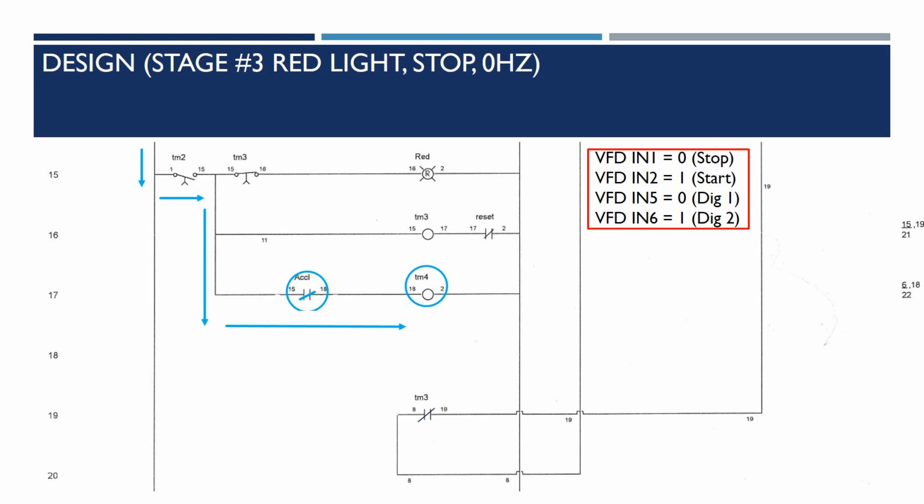That coil has been programmed with a 10-second time delay, which is the penalty that is applied to the boost button. So your 10-second penalty either starts in one of two conditions. When you let go of the accelerator button, that will open that contact back up and shut power off to TM4, which would start the timer, or when we have our normal reset signal and the light transitions back from red to green, that would start our 10-second timer. So you can control when your penalty is applied. So when you do run the red light, the sooner you let off that accelerator button, the quicker your time delay starts, and the less time that will cut into your next green light.